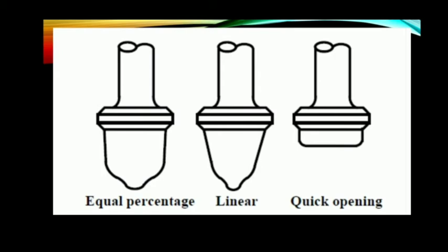The valve characteristic shows that a relatively small motion of the valve stem results in the maximum possible flow rate through the valve. Such a valve, for example, may allow 90% of maximum flow rate with only a 30% travel of the stem. Linear type. This type of valve has a flow rate that varies linearly with the stem position. It represents the ideal situation where the valve alone determines the pressure drop.